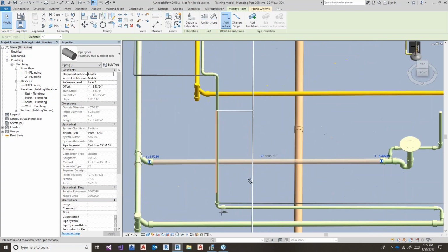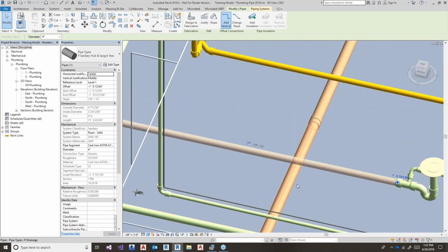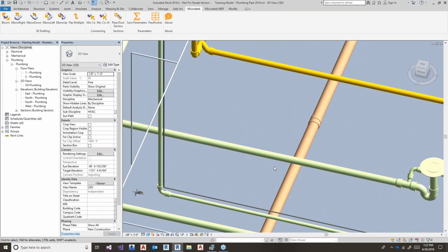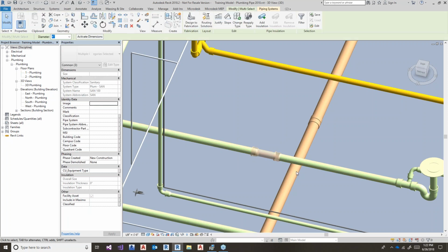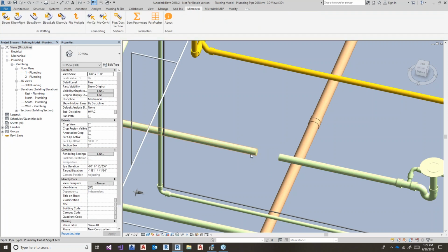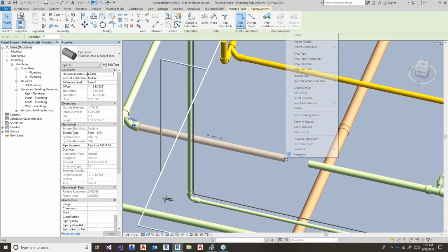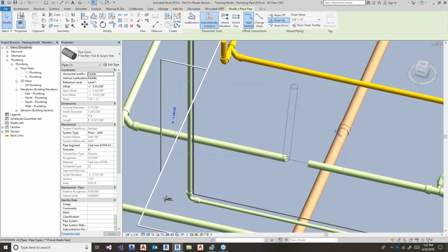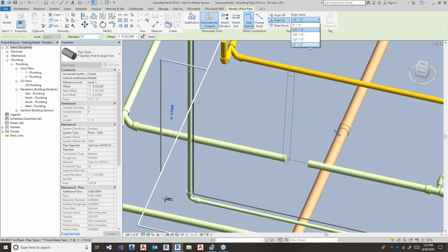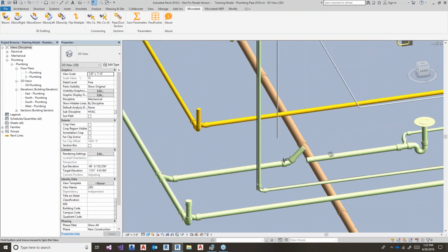And then, of course, it's possible too that maybe we've got a below ground drainage pipe here. We've got some perforated PVC, and maybe we need to route around that. So if I just use Revit's split command, SL is the keyboard shortcut, and I create a gap for myself, then what I can do is come here and maybe draw a pipe again at that 12-inch over 12-inch slope. And that puts the 45 in.